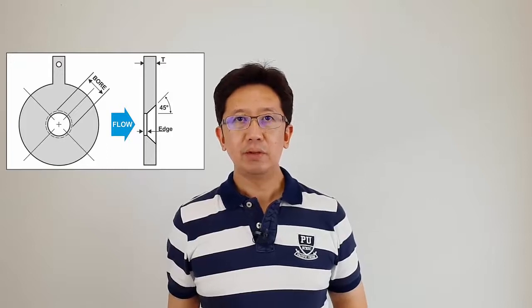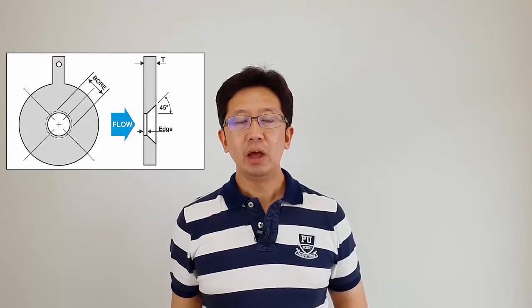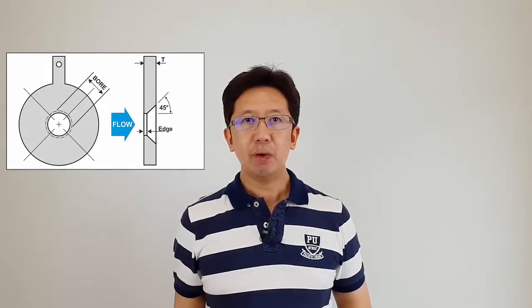What is the orifice plate? Orifice plates are the simplest and cheapest of the differential pressure flow elements. The equipment cost is relatively independent of the pipe diameter, and installation is consequently relatively expensive in a small pipe but very economical in pipe sizes above 6 inch. Orifice plates can be used in a wide range of applications. There are many types such as concentric, segmental, or eccentric.